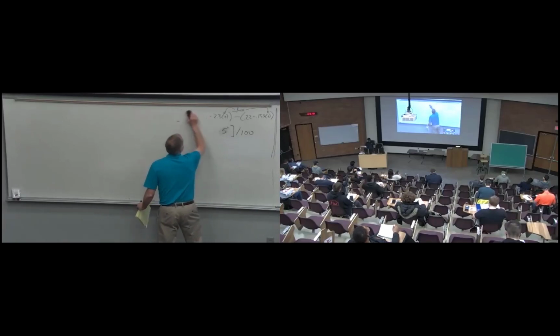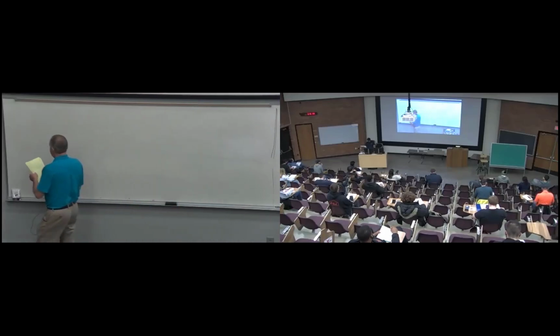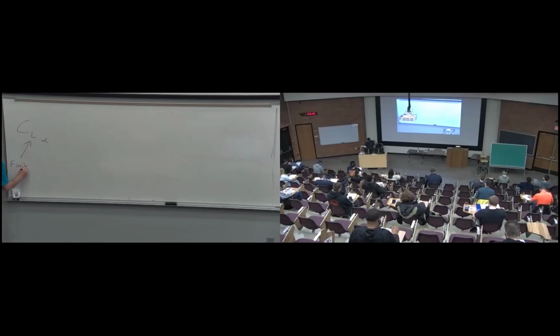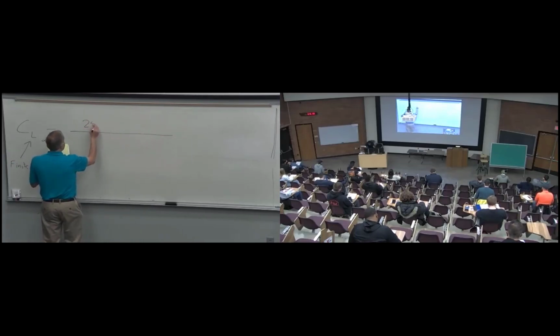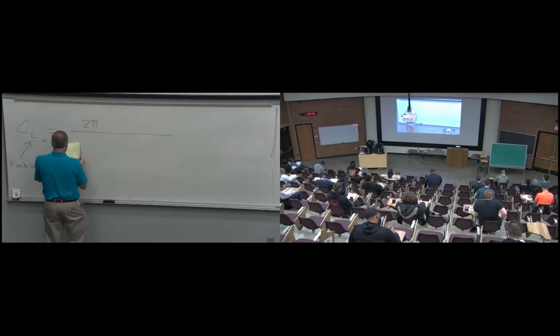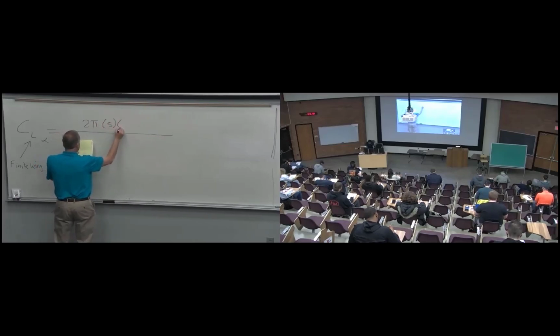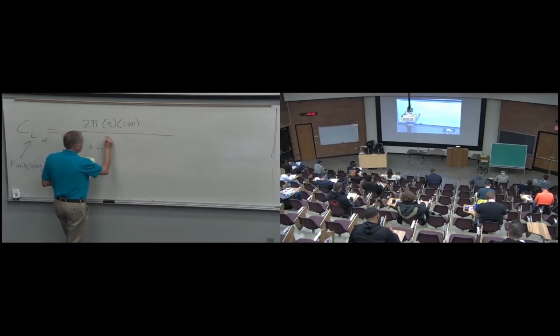Big formula, so I need a big room here. So this is the lift curve slope. Notice capital L, so this is a finite wing. It's going to be 2 pi times the aspect ratio times big K, because I brought those over, multiplied through. So that's the numerator. The denominator, I got 2 plus the square root of a whole bunch of junk.